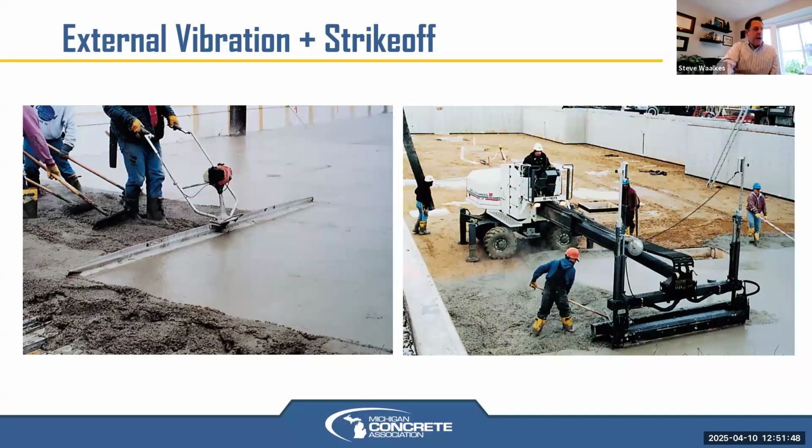The VibraStrike or Copperhead on the left has some vibration to it. That's why it's got a motor mounted to it with an eccentric weight to give it some shake. And then the laser screed on the right does a great job of accurately screeding off the surface of the concrete with a 3D profile fed into it, and can result in very, very accurate elevations for that concrete slab, floor, parking lot, or whatever it is.